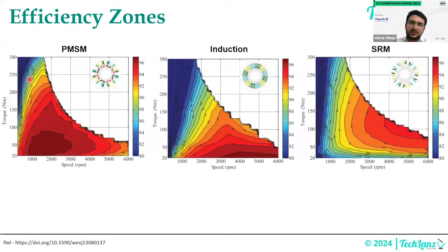Now, just to mitigate this issue, I'll talk about some more things. Sometimes people think the PMSMs are extremely efficient, but people don't look below this. In the low RPM and high torque zone, which is the starting application, especially in Indian stop-and-go traffic conditions, it gives you around 30% efficiency. So the PMSM also is very inefficient in very low RPM and high torque zones, which causes the problem. When you expect your vehicle to give very good range, even the PMSM does not deliver, because you're not operating in the peak operating zone. Forget about the induction motor, which anyway has poor efficiency in this region.